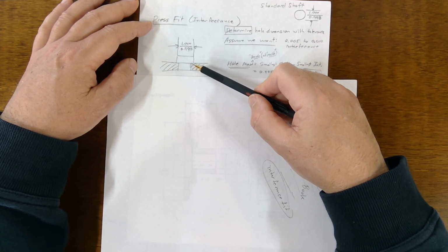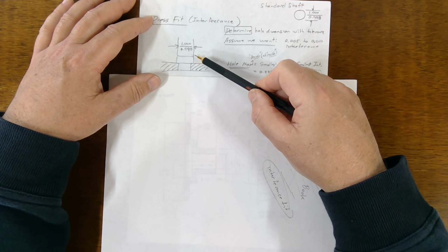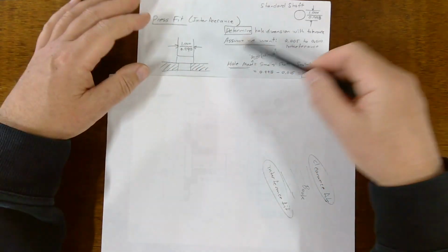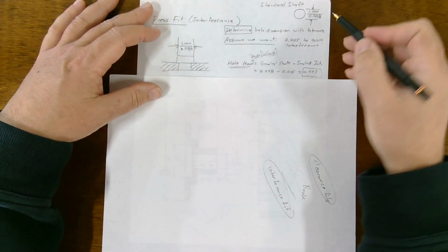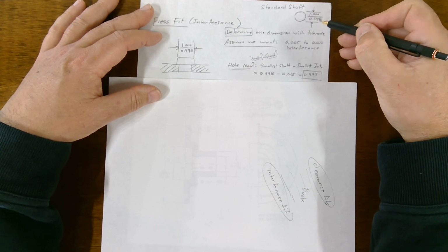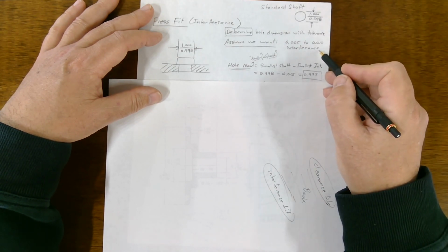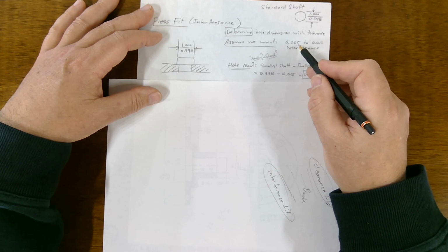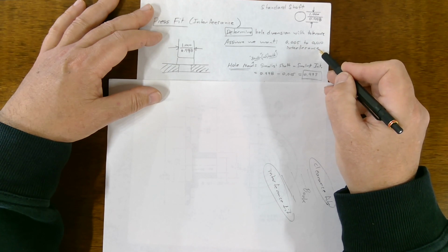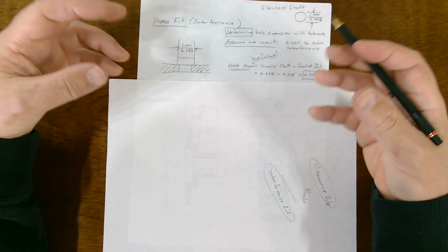A really simple example is a nail, where you just pound it into the wood. But we do this with metal and parts all the time, where to assemble them, we just specify these tolerances and we just press them together and they stay together. So let's use our same shaft, 1.000 and 0.998. And somebody somewhere comes up with this interference, right? Like 5 to 10 thousandths interference. Somebody decided that this amount of interference will serve our purposes. It'll make the parts stay together.